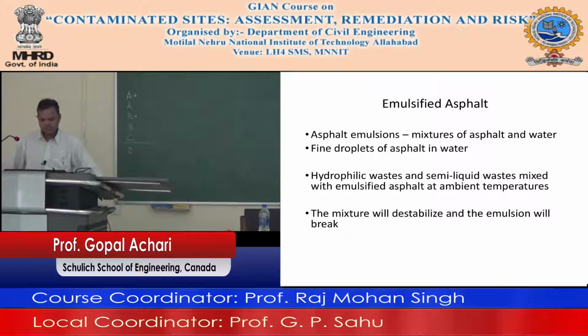Then what you do is you take the hydrophilic waste and semi-liquid waste and treat it with emulsified asphalt. You take the waste and add the emulsion, these fine droplets of asphalt in water. What does the asphalt do? It goes towards the hydrophobic material. Once the mixture destabilizes, the asphalt goes after the hydrophobic material and covers it. Asphalt is very hydrophobic, and eventually the whole thing settles out as a globule.